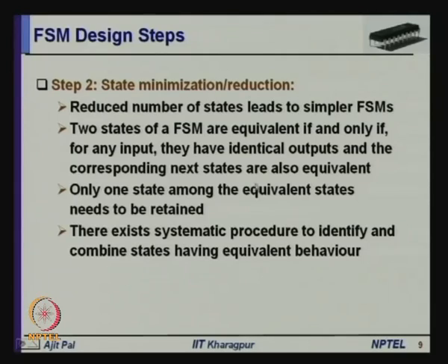So, one important step is state minimization, and how is it done? Actually, 2 states of a finite state machine are equivalent if and only if for any input they have identical outputs and the corresponding next states are also equivalent.